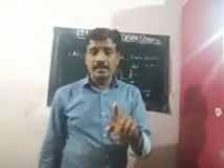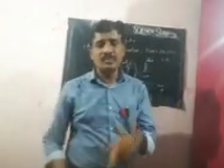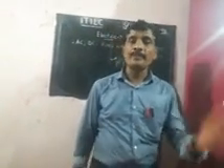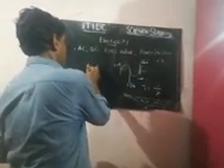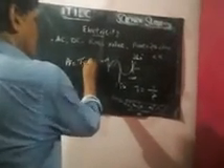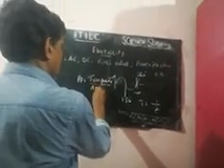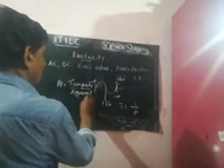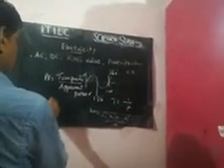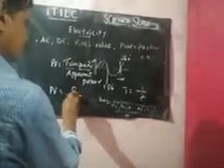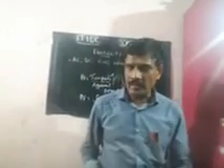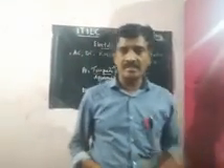That's why the power factor is the wattmeter reading power divided by V into I. Power factor can be represented by the equation PF equals true power divided by apparent power, or power factor equals R by Z, where R is resistance in the electric circuit and Z is the impedance in the electric circuit.